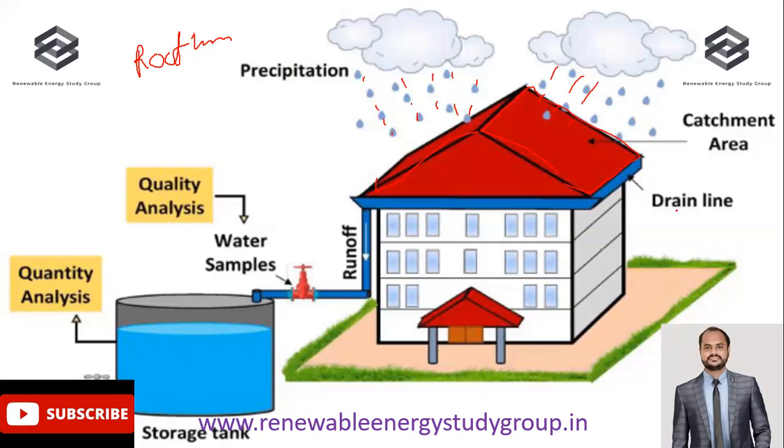Thereafter, we utilize this drain line, or we can say the gutter system, where all this water falls on the drain line, and further the flow is channeled to the sprocket or the runoff pipe, and thereafter it is given to the storage tank. Some storage tanks are developed or designed underground also. Some storage tanks we can also design on the surface, based upon the system.